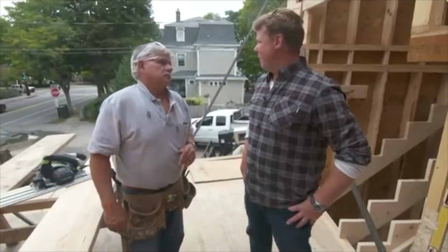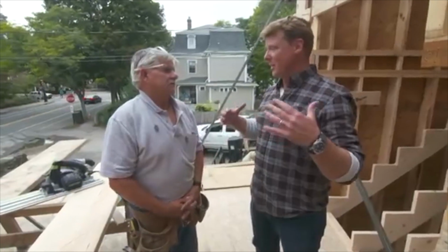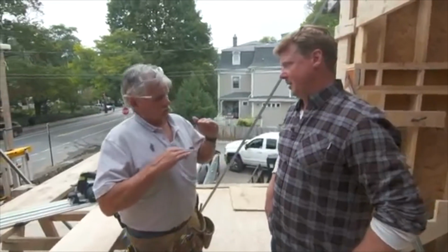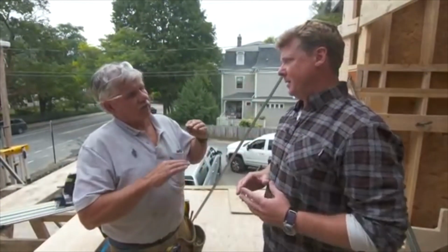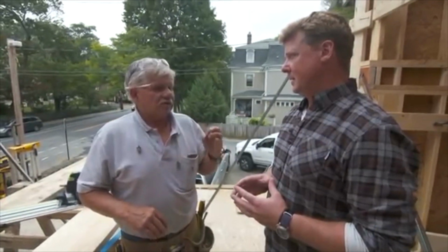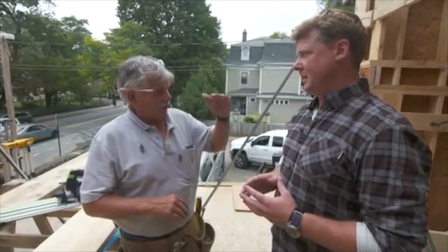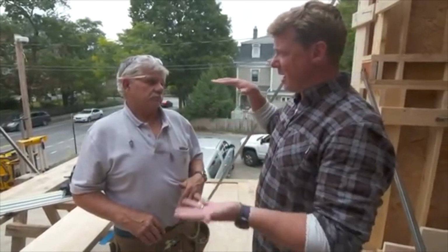So when I'm thinking about building stairs, or when you're thinking about building stairs, what are the 2 or 3 things that you have to get right? Well, you have to get the riser height correct. That's our step up from one step to the next, the riser. That's right. And you have to think about that being a comfortable step up. So 7.5 is the magic number that you try to get to. Yeah. Under 8, over 7 is always comfortable. Right. So that's a good size, and they can't vary that much from step to step.